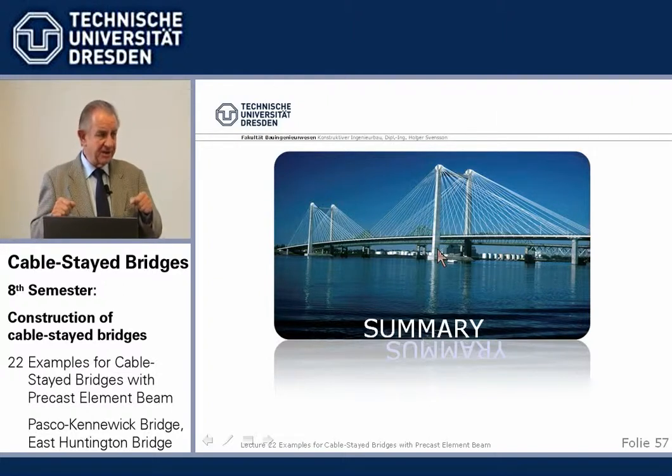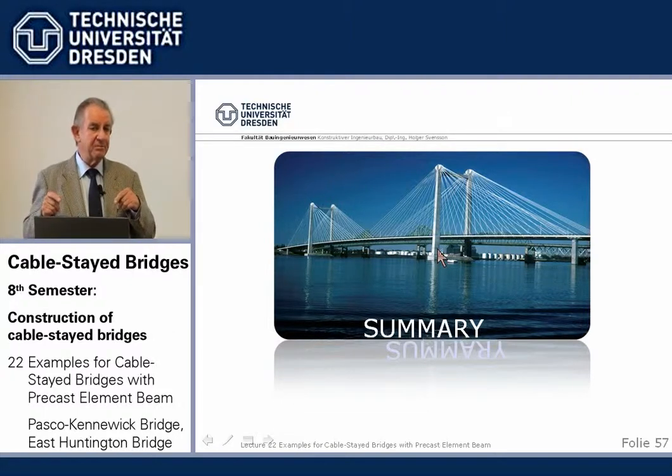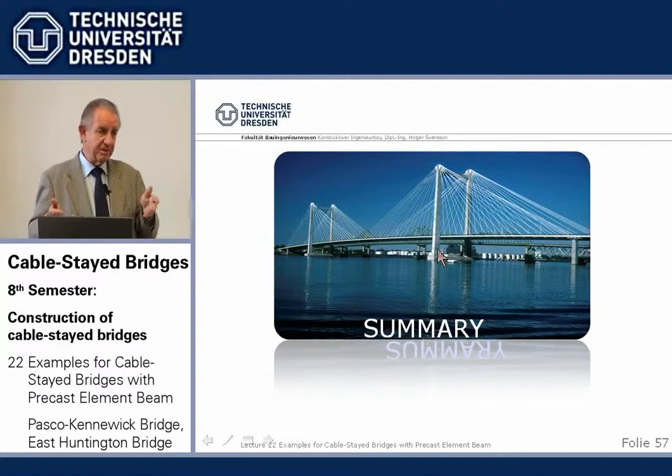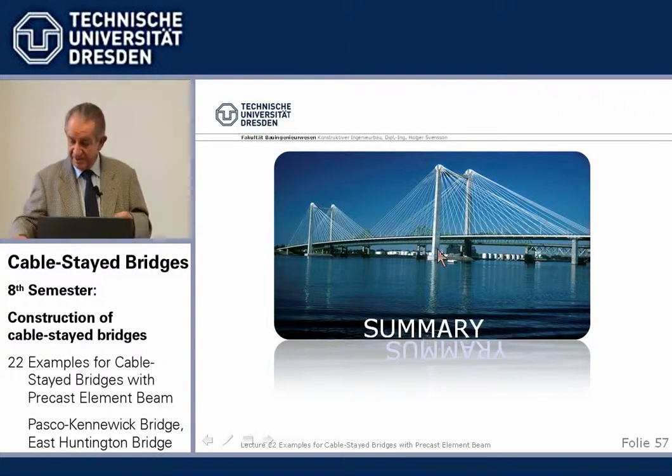It's absolutely watertight. You have less shrinkage and creep once they are installed, because they are, say, 1 year on average old. So most of the shrinkage and creep capacity is already gone. Those are the advantages.